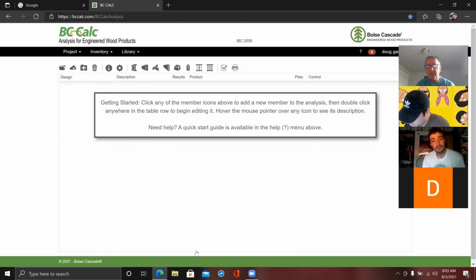But I want to show you, and I don't think I've done this with you, I might have done this with Calc 1 and 2. When I draw house plans, this is what I do to calculate a beam. I'm not using that 5WL to the 4th over 384EI. As I mentioned, number one, that's not the only calculation I have to make. I also have to calculate the moment on the beam that we discussed yesterday. What was it? WLx over 2 minus Wx squared over 2. That was the moment on the beam too.